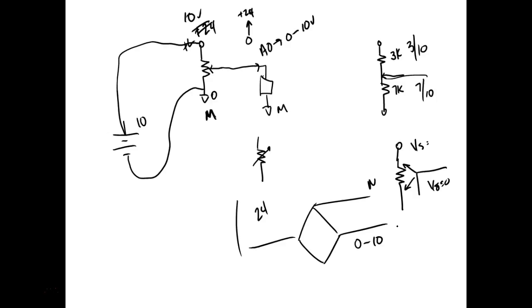This guy here plugs into 120 volts AC. Then it's got a built-in 24 volt power supply that I can use out there on my input devices, because all the inputs are DC inputs. So on PLCs, if it says DC, it's talking about plus 24 volts. That's just the standard that we use now.